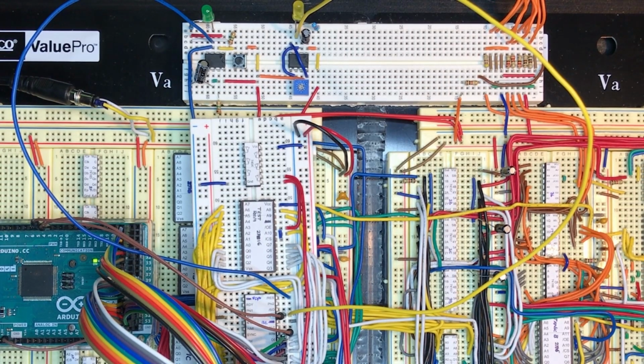Okay, so we've got the hex file burned to the EEPROM and dropped back into the circuit. The circuit is connected up to the slow clock driver circuit and a debounced reset switch. The slow clock circuit uses a 555 timer chip to create a slow pulse that will drive the 6502 CPU. I'm using it as the Phi0 input on pin 37.